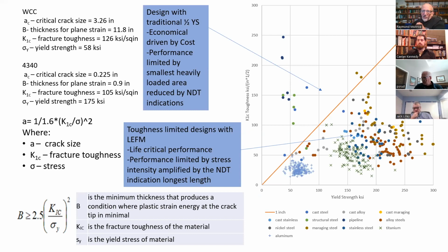I think we do want to do the test block next time, and I'll try and get some solidification stuff together for the test block. I especially want to talk to Charlie about looking at the lines of symmetry and the changes in cooling rate in normal test blocks, wedge blocks, to show that there are certain regions that are problematic. And we actually have data for high strength materials as a function of how far away they are from the bottom. And of course, they drop dramatically as you get towards the center line. So I think that could be useful.